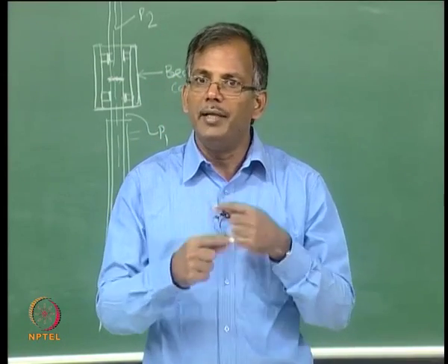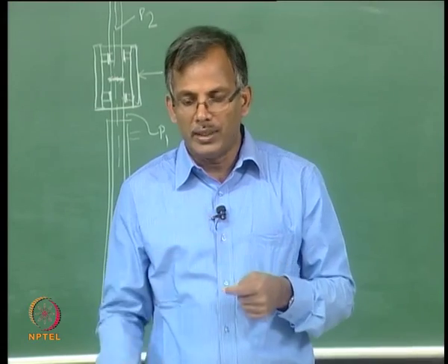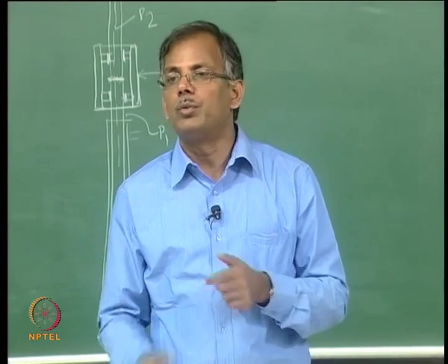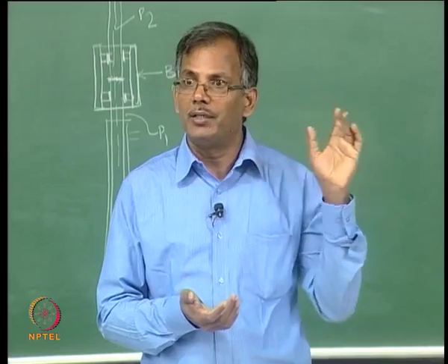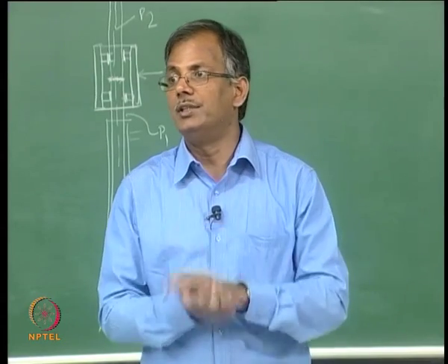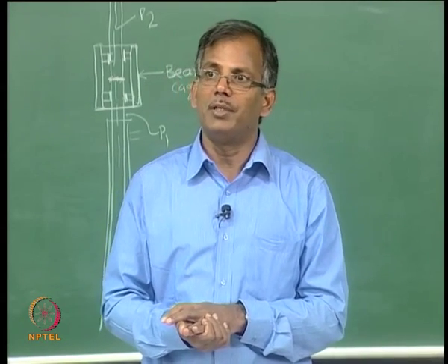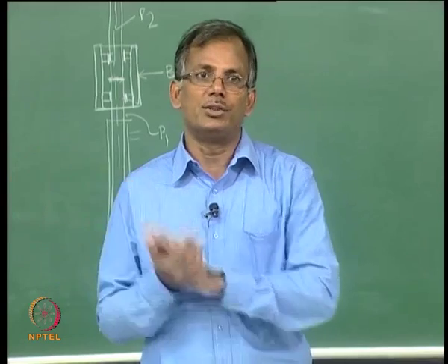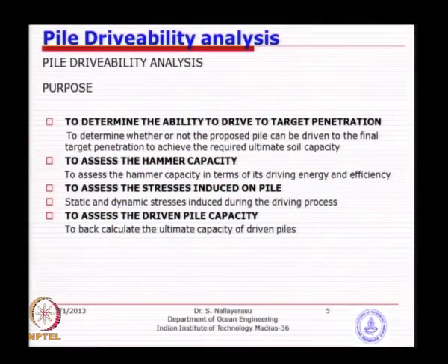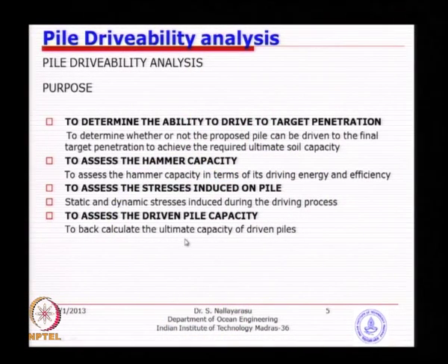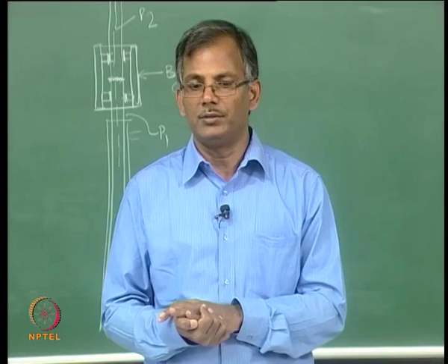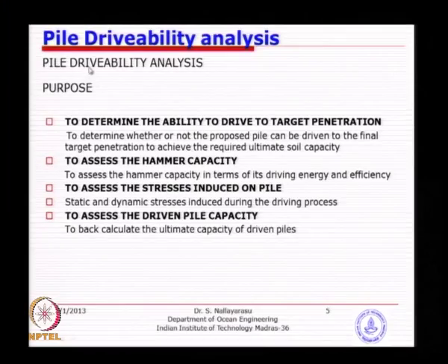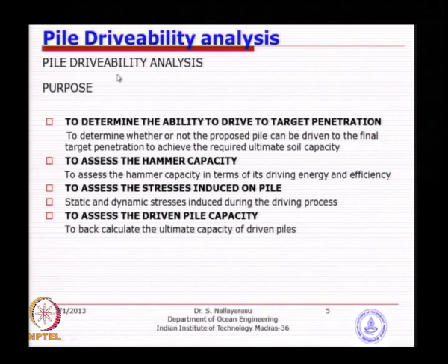Then we devise an idea to calculate the capacity backwards, which is also possible. Though we cannot do real time testing, we could at least achieve some capacity calculation based on the site records. So, that is one of the possibilities, where we will derive some equations to do that exercise, because we cannot anyway do the pile testing. That is why pile drivability analysis becomes a most critical part of the whole offshore project, because this can turn the project in any direction.